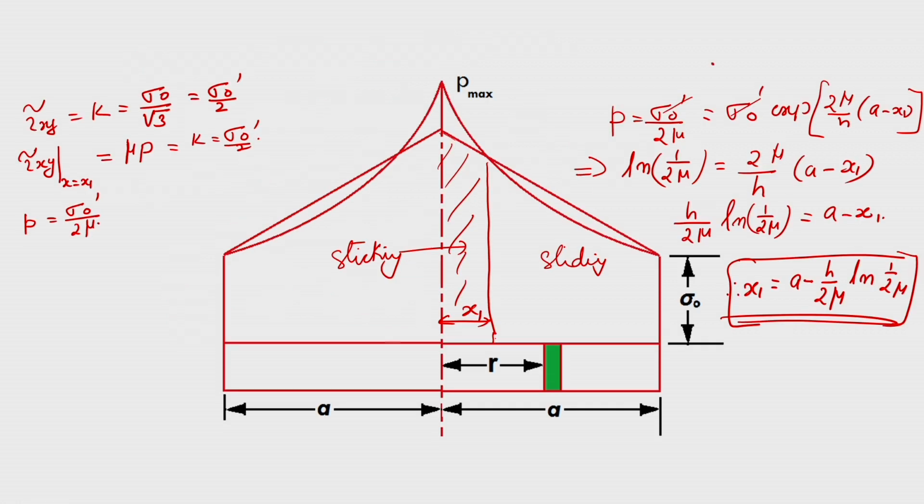You can just integrate from here to here using the mean stress, and then from here to here you can integrate using the earlier equation, and then find out the sum of all those things. So, that is what we can always get. Now, once you get this, you have to multiply by the width of the specimen, so that you get the total load. This is what we are calculating for unit width. So, you have to multiply with the total width of your workpiece, and then find out the total load which is required for this forging.